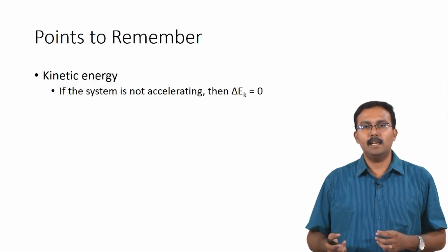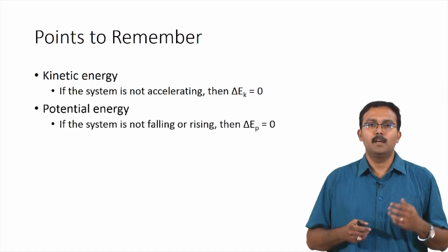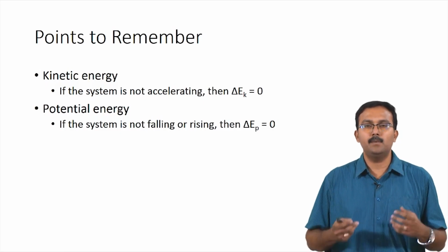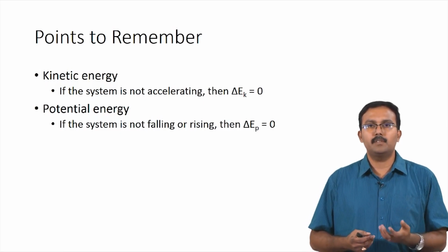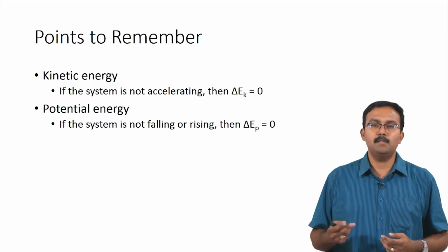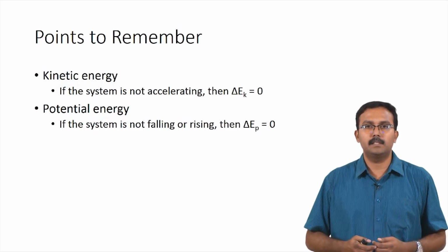So, this change in kinetic energy will be 0 for non-accelerating systems. Potential energy would again be the change in potential energy, which means as long as the position of the system is not changing, that is, the system is not rising or falling, then the change in potential energy will be considered to be 0 for performing energy balance calculations.